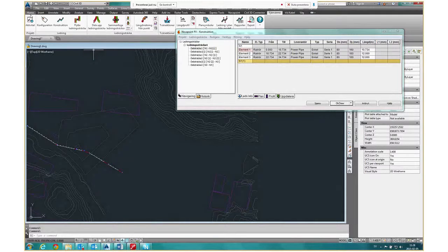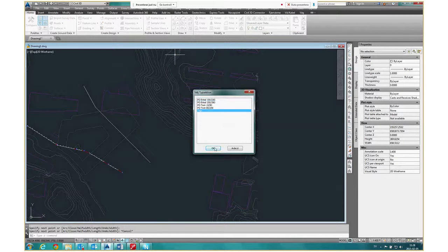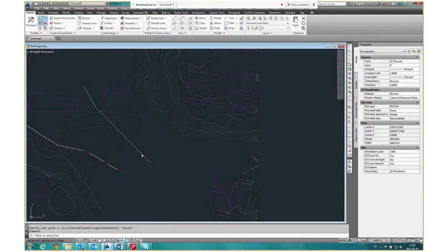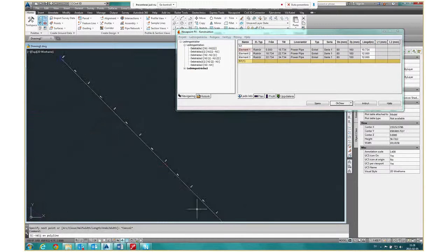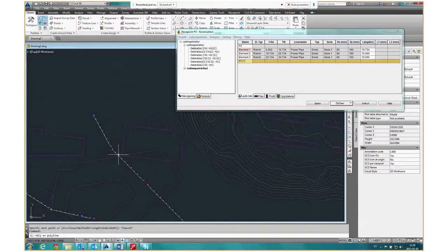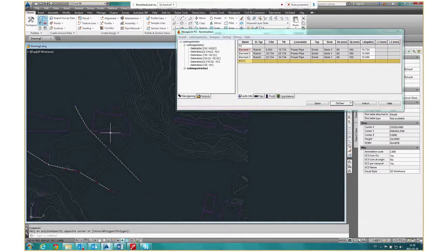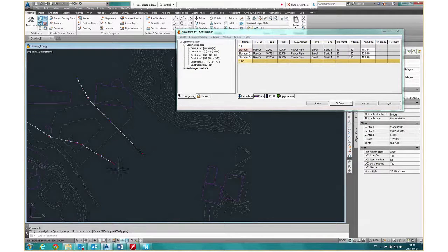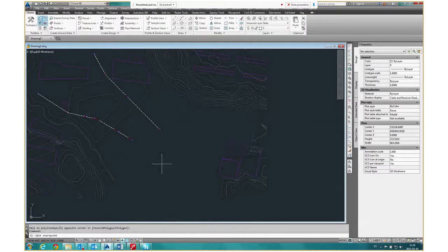If you want to go from a polyline like this, you can just take this choose line and just click on the polyline, and it converts to a Novapoint district heating directly. And then you can work with, put in bow pipes or bows. Or the third alternative is that you do it more detailed between each node.